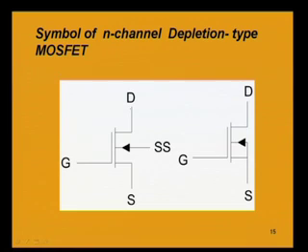These are the three terminals, drain, gate and source. The substrate terminal is this one, and it has the direction of the arrow signifying whether the substrate is p type or n type, and we are considering an n channel MOSFET. The substrate is p. So, as the substrate is p, the current direction is from p to n, that is why it is in this way.